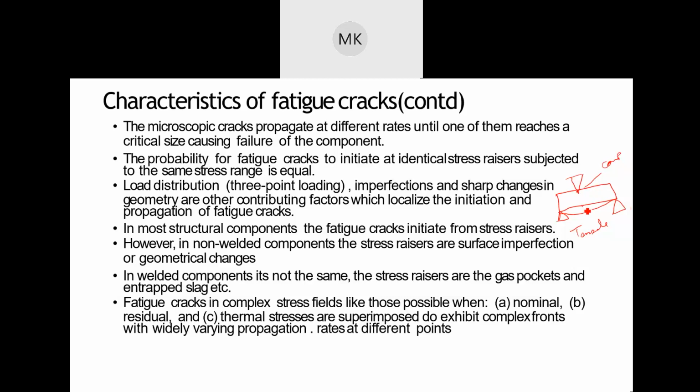It's going to start somewhere over here after this tensile loading reaches a particular plastic deformation, that the crack would start from the center spot opposite to where the load is being applied, and then the crack would grow along and reach failure like that. So in a 3 point loading, depending on the load distribution that you have, you are localizing the area at which the crack is going to initiate, propagate and go to failure. And most of the time, if it's a ductile material, your crack is going to start on the opposite side where extension is going on, and then basically grow upwards to failure.